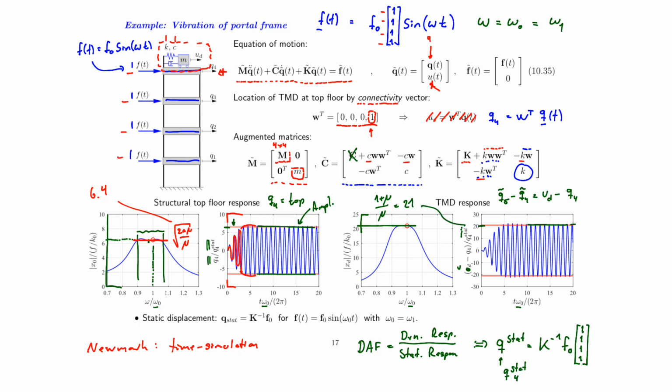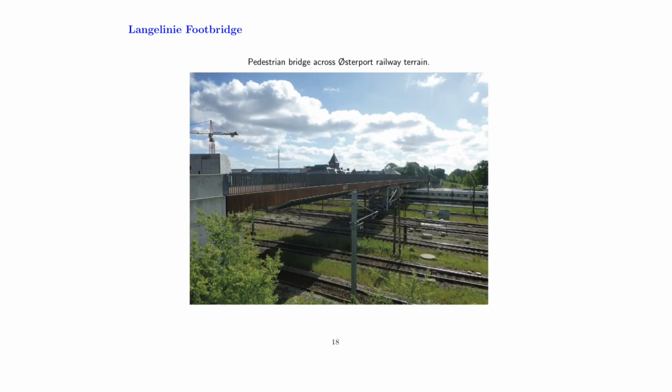So again, it's quite easy by a frequency response analysis to immediately get an idea of what the amplitude is during steady state. And you know that for resonance, we have a minimum overshoot in our time response curve. So the steady state value is actually also very close to our maximum deflection. And that is why frequency response analysis by figure 1 and figure 3 is such a strong tool, because without simulating full time series, it can actually provide us with amplitudes at resonance. And in many cases, we design our structure directly to resonance, assuming that we have a time harmonic loading on our structure.